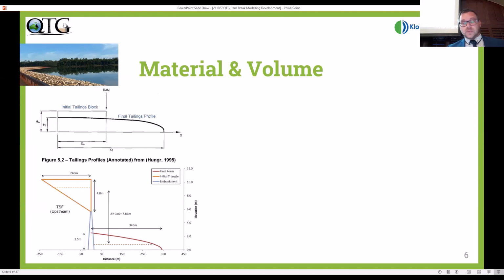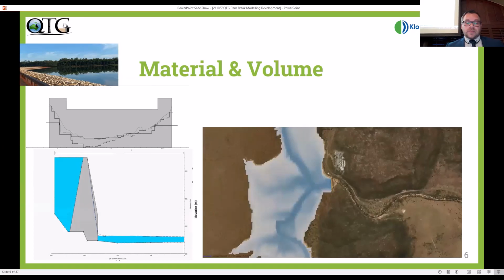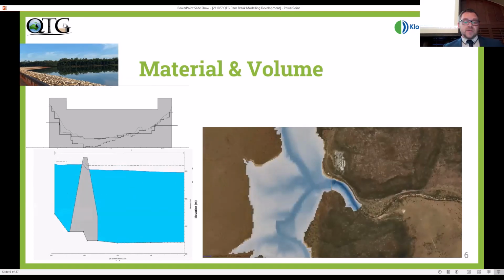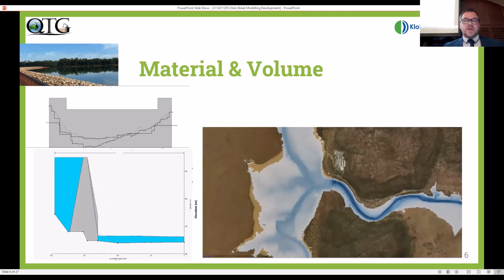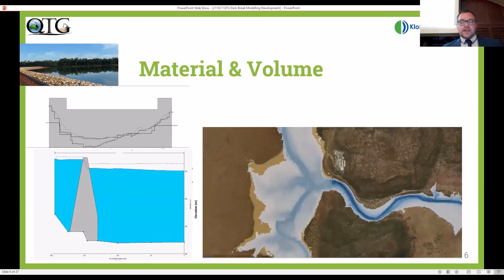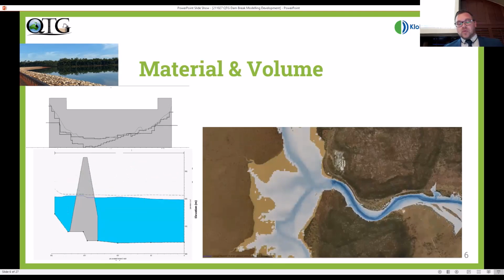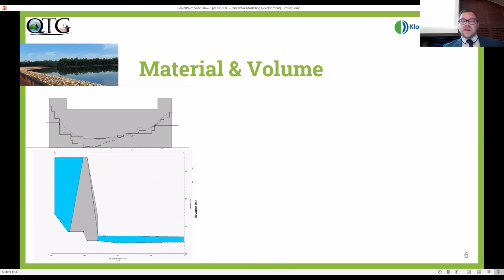There was no run-out. Well, that was the run-out extent. At the time, that was a fairly simple analysis, but it also wasn't uncommon to see non-Newtonian behaviour being completely ignored by modelling the facility as water. Sometimes this was due to the absence of information, sometimes it was due to limitations in software or expertise. The outputs were generally presented as being conservative, however, there isn't really a whole lot of evidence to support that position. Ultimately, these methods ignore most, if not all, of the flow properties and characteristics of the material that are actually within the TSF.